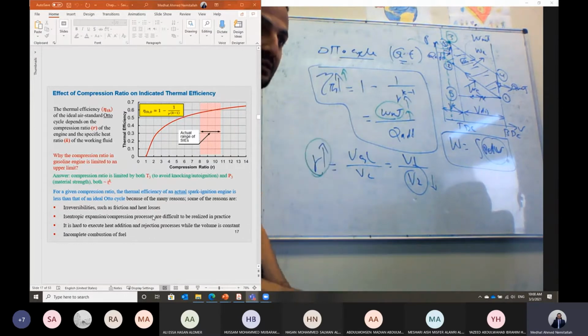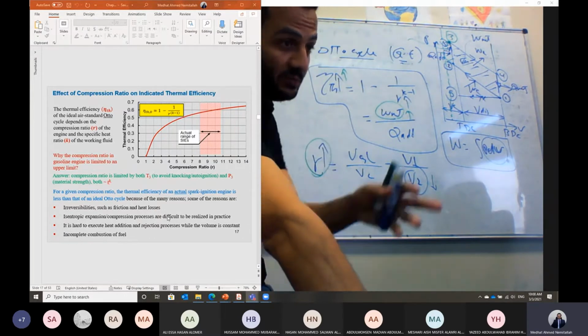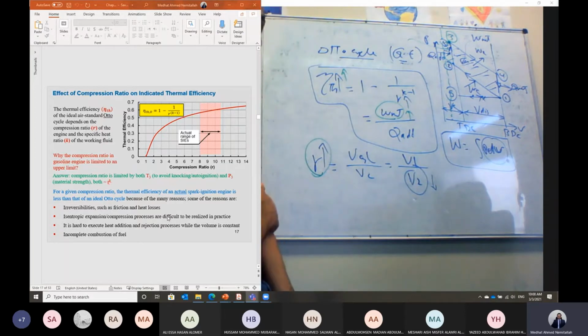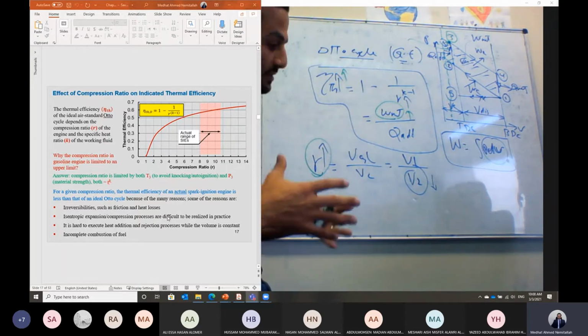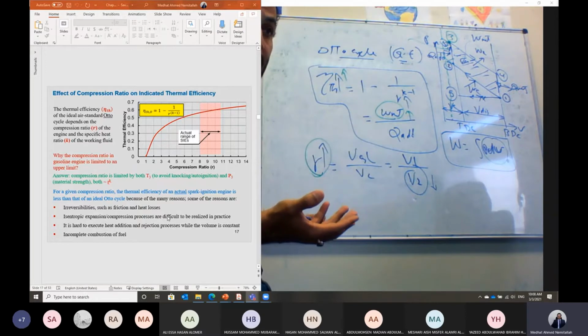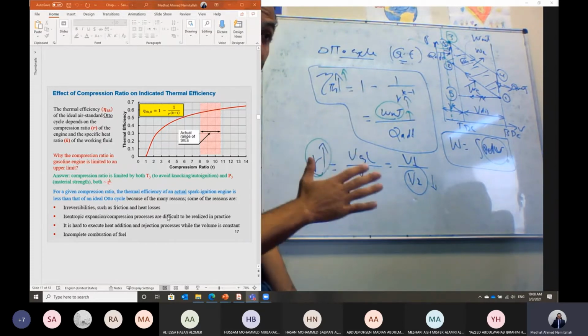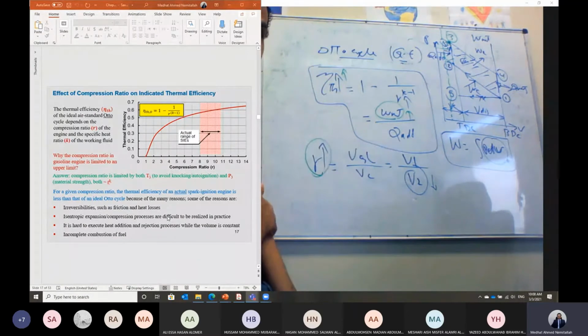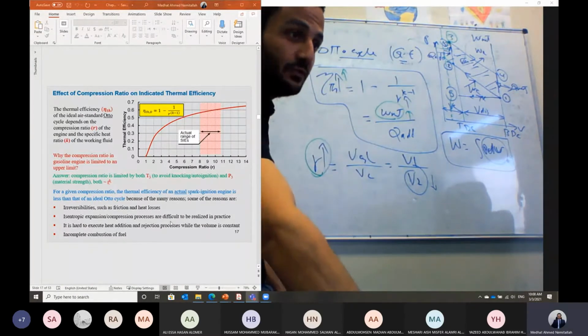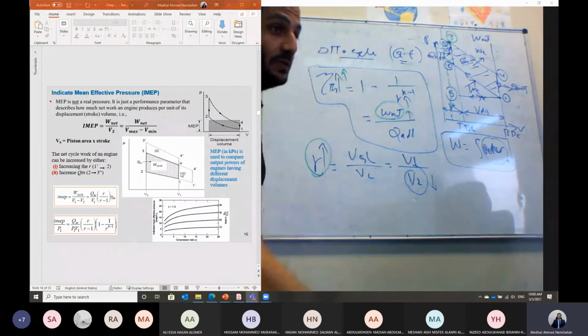All of these assumptions result in the limiting, or maximum, efficiency of the engine. In this case we also assume we don't have any heat losses within the system. In a gasoline engine we have a cooling water circuit and oil for lubrication, and those two systems can consume about one third of the output power of the engine. It's absorbed by the cooling system. So the efficiency of a gasoline engine is about 30%.